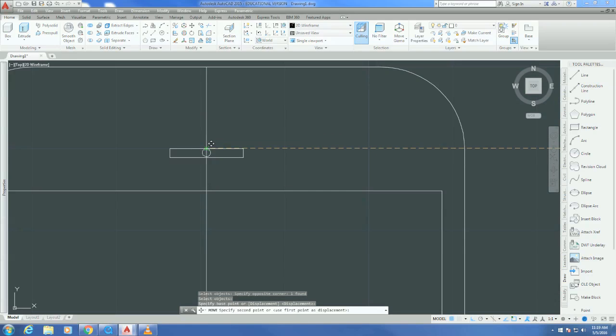And then we're going to move it up. Using the snap cursor to 2D reference point. And we're going to turn off that snap button. They kind of don't like to work well with each other.